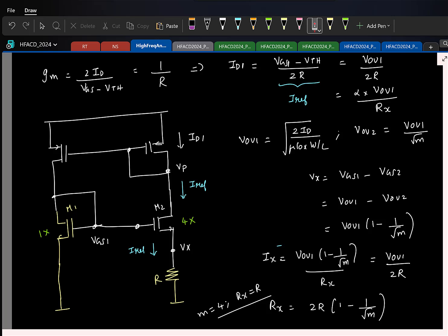So this is one common way in which this is done, but which one? Yeah, that's what this will typically be, an off-chip resistor. So you have very good zero temperature coefficient off-chip resistors, right? So yeah, this should be an off-chip resistor. Else you have to do something on chip so that this is a constant, right? Okay. So this is nice.